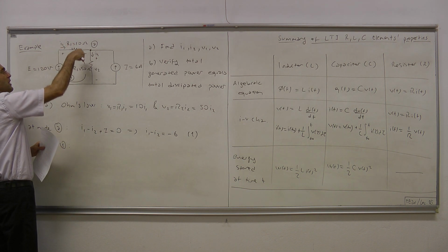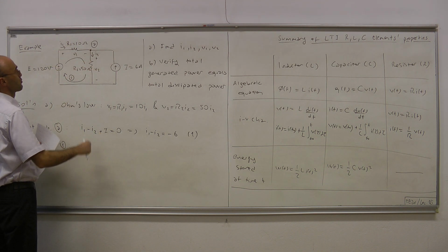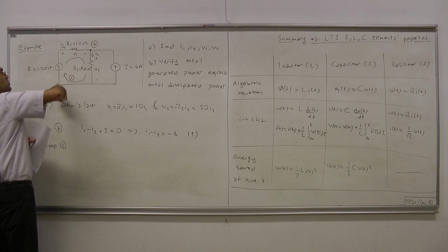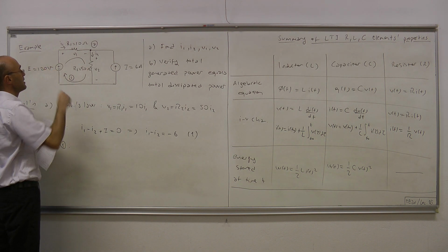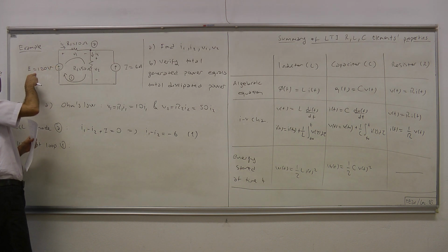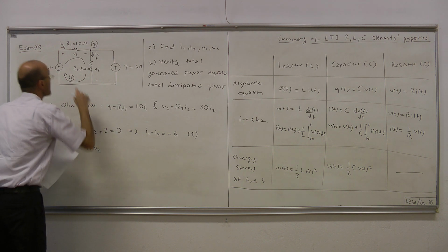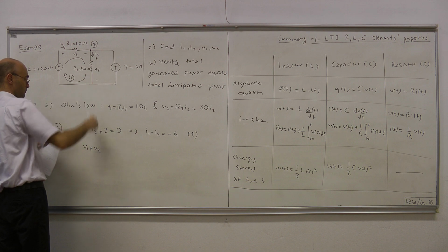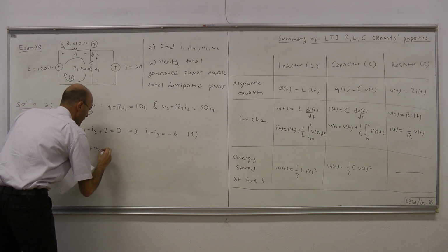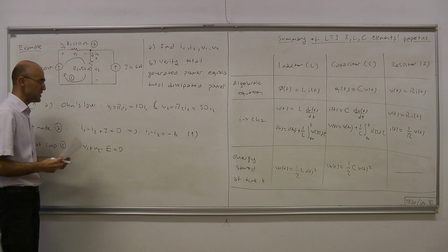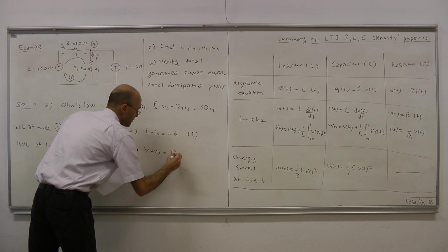The first voltage is V1 plus minus, the second voltage is V2 plus minus, so everything should be plus minus so that we can write the equation properly. Finally, we have this voltage, but it is given as minus plus, which is only a minor difficulty. We can make it plus minus by negating the 120 volts. So we have V1 plus V2 minus E equals 0. E is given to be 120 volts. Therefore, V1 plus V2 equals 120.